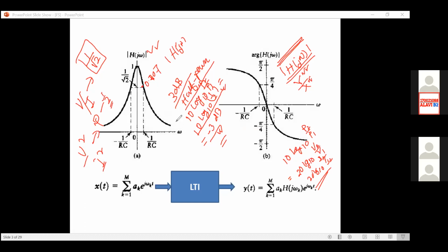So in this way, you can easily see that someone was telling that it is the cutoff frequency. Actually, theoretically, we cannot determine exactly the cutoff frequency of our RC circuit. The reason is that the curve is something like this, but the ideal is something like this. If we have a low pass filter, for example, and this is your frequency omega, the characteristic of a low pass filter transfer function will be something like this. This is your omega C, the cutoff frequency. Within this frequency range, you have a constant gain, but beyond it, we don't have any gain.